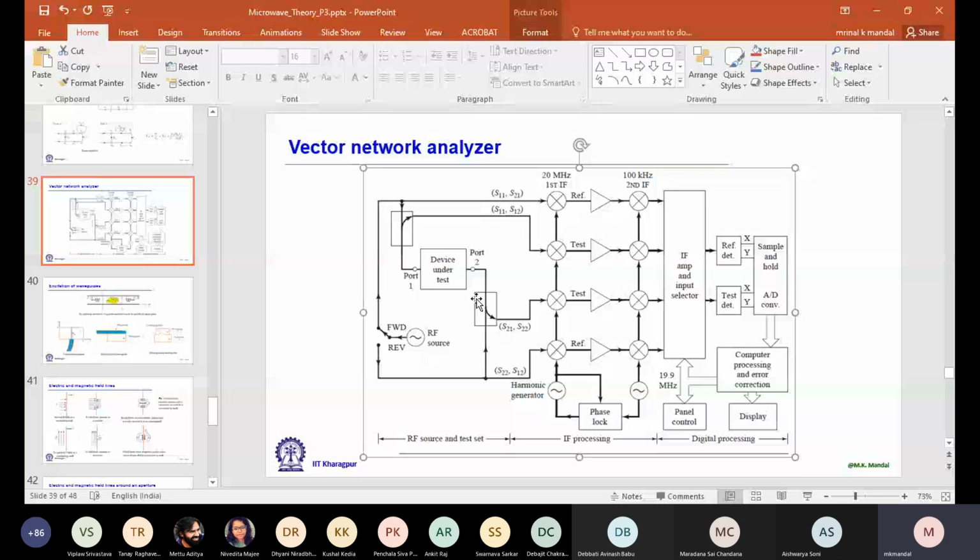Well, so we connect them one by one between port 1 and port 2. And inside the computer, it is already loaded with the program. Then it measures these devices and calculates the error matrix. So basically these 4 individual devices work like reference planes. With respect to that, we calibrate it.